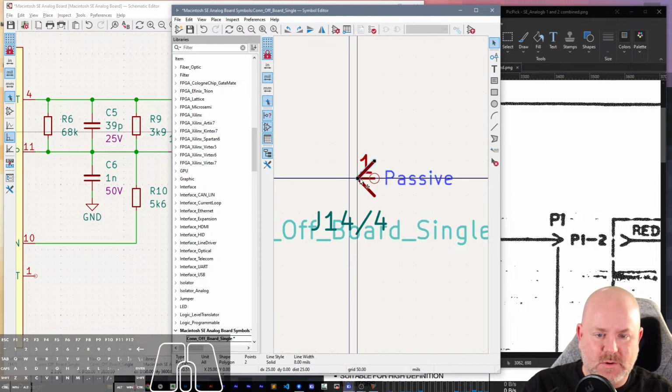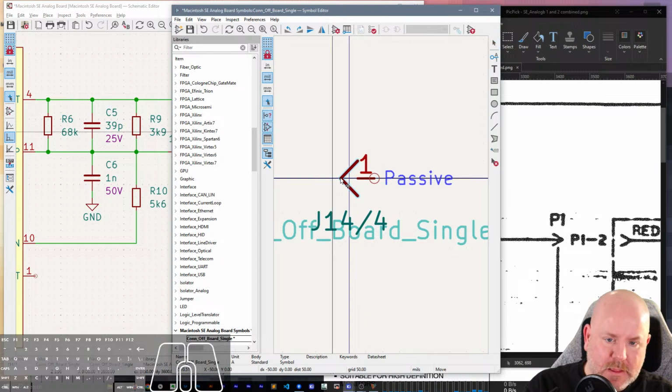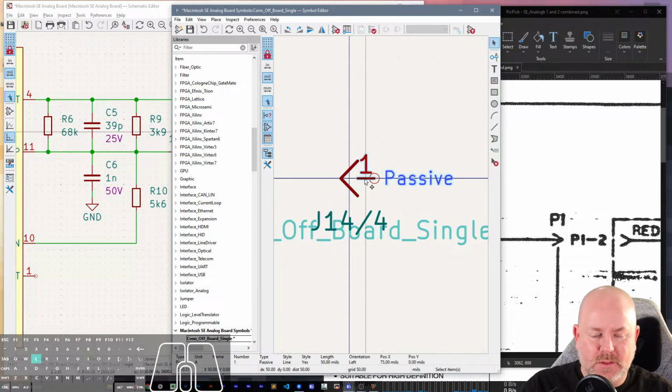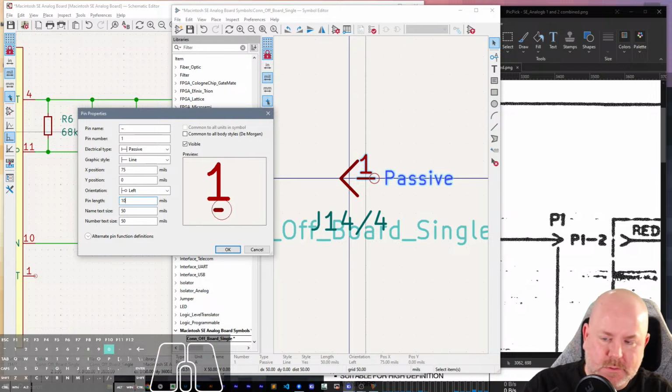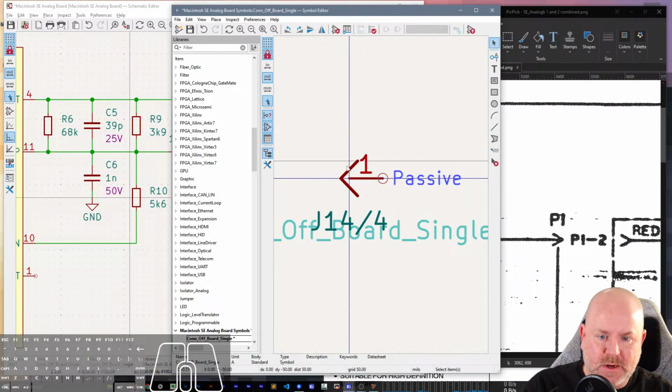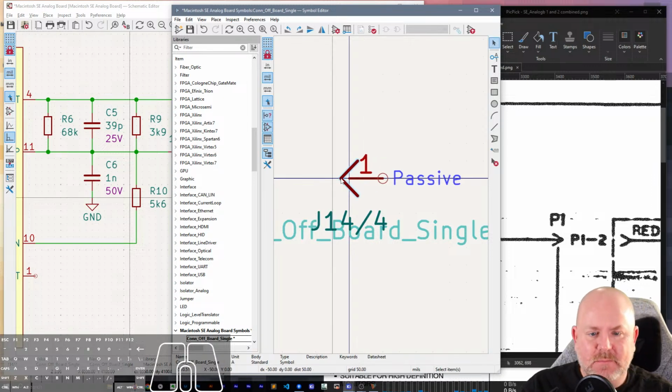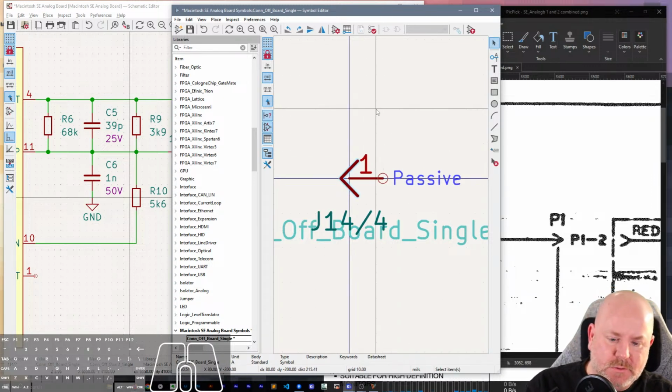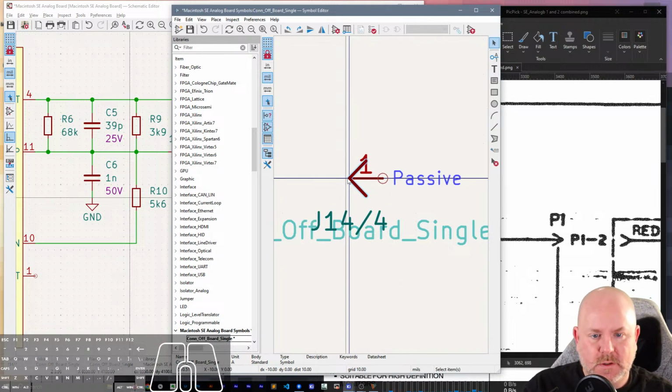And then we're going to move them both. That looks good. And then on the pin, I'm going to make this 100 mils. And then can I move this to about there? And then these, if we move them back, I think my graphic override, maybe if I do in to 10 mils and then do move there. That's what we're looking for.